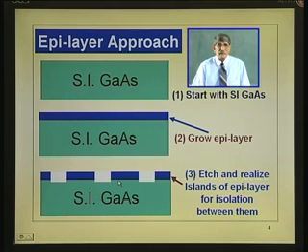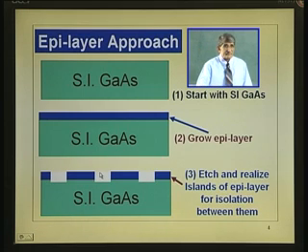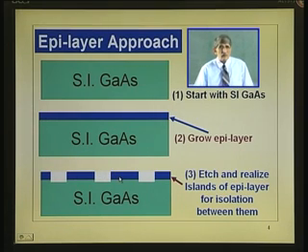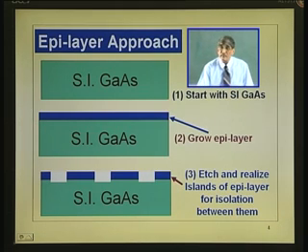Sometimes people may object to a structure like this, because the wafer top surface is not planar, it is varying like that. That is objectionable if this layer becomes too thick. If it is say 0.1 micron of that order, you do not have to worry much, because that step anyway you get in the oxide itself in silicon technology. But even there, when you want to go for more and more packing, reduced dimensions, then you do not like these ups and downs at all. You have to do some planarization technique. Here there is a totally different approach.